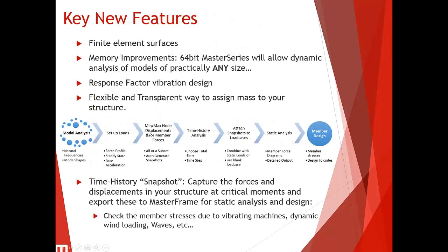So here's a list of some of the features that have been introduced over the past year. Some of the key ones, I suppose. Finite element surfaces. This is the biggest thing that we introduced in the last year. So it's now possible to dynamically analyze models with FE surfaces, and this includes composite floors or slabs with attached beams, like Martin was showing you earlier. We can do shear walls, and anything really that you can model in finite element surfaces can now be dynamically analyzed.